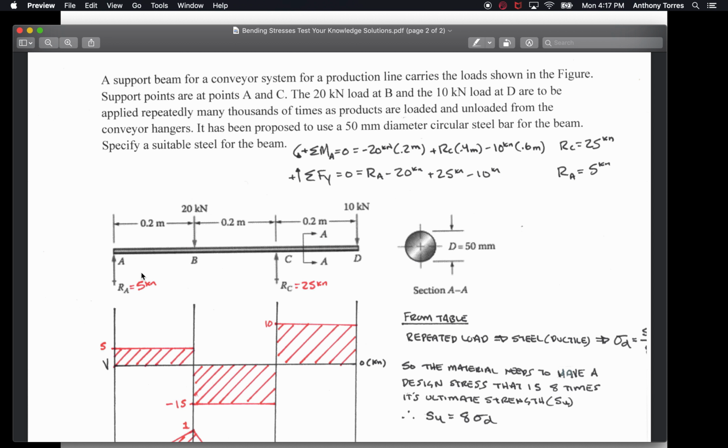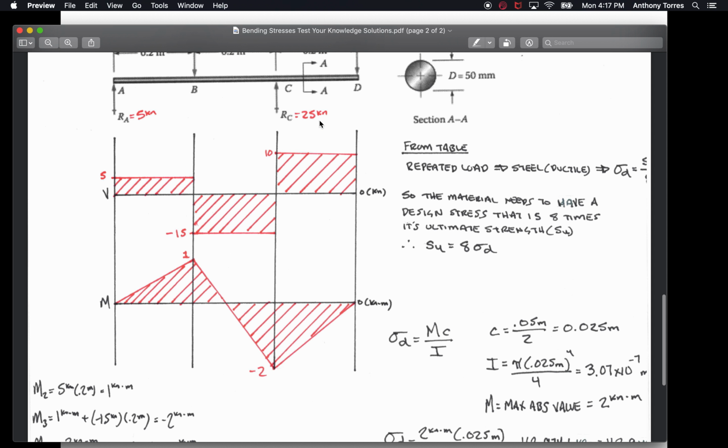Then I've gone ahead and produced the moment diagram. Let's focus on this first, not all the math everywhere else. So I've drawn the line vertically downward at every load. I have labeled that this is the shear line. It is 0. Kilonewtons is my unit, so I don't have to write that every single time. This is the moment 0 line, and the moment is in kilonewton meters. Units also written, so I don't have to write that every single time.